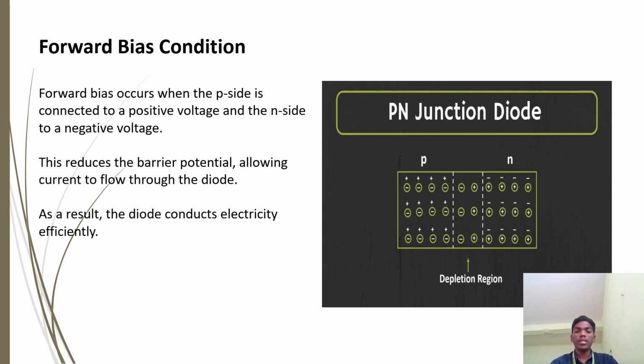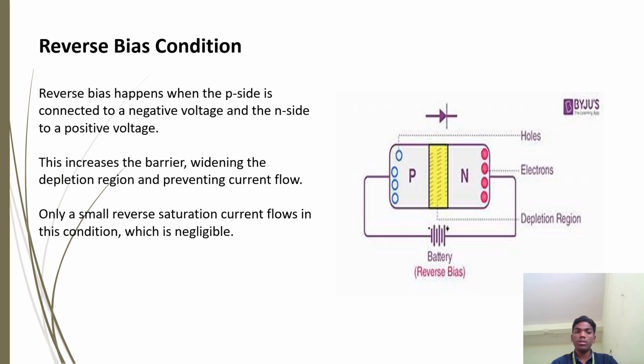The P-type semiconductor is connected to the positive terminal of the battery, and the N side is connected to the negative terminal of the battery. Due to the external DC voltage, the charge carriers will move from P-type to N-type material. After moving, the charges present in P-type get neutralized with the N-type material, and due to this neutralization, the number of charge carriers is reduced, and the length of the depletion layer also gets reduced. As a result, the flow of electrons produces a current in the circuit.